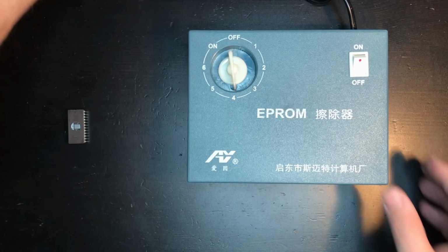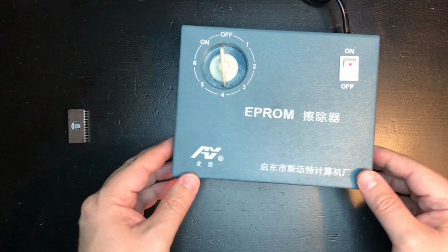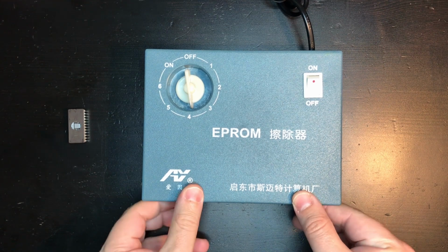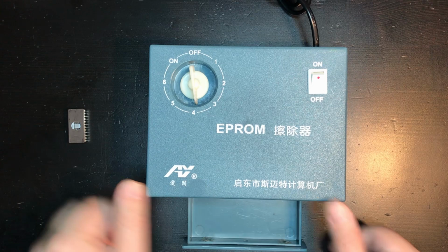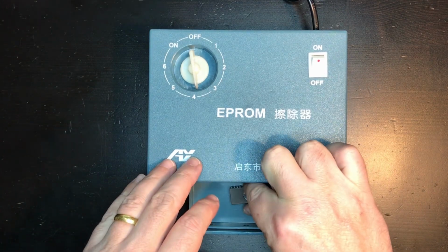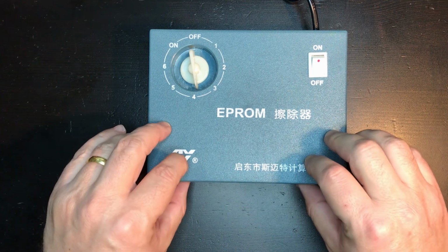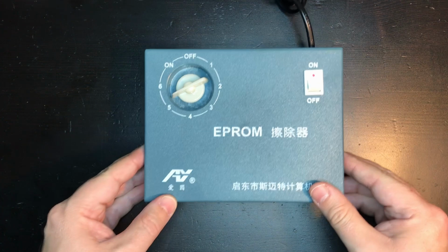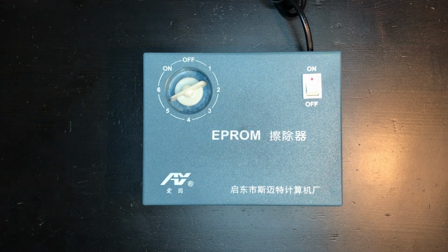I'm showing here the device to erase an EEPROM. It's simply just a plastic device that has a drawer to place the EEPROM chip, a switch to turn on the UV bulb, and a timer to auto switch off the bulb. Typically 10 to 15 minutes of UV out of these and it will be erased. Note that they are raised to the FF hex state, or fully on, not the 0 state.